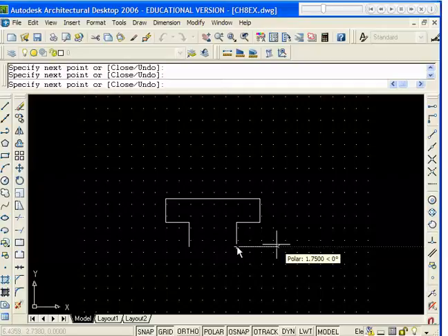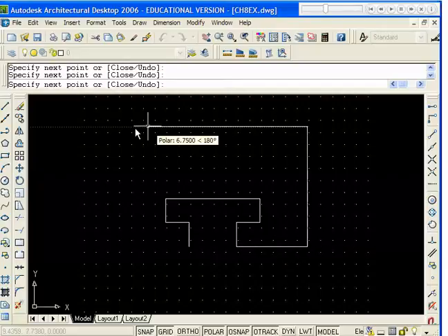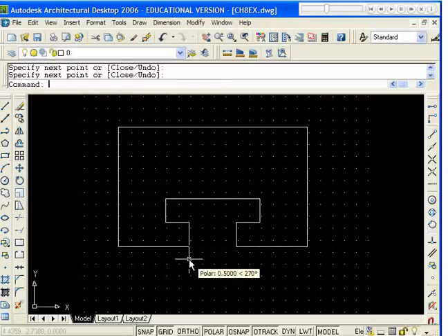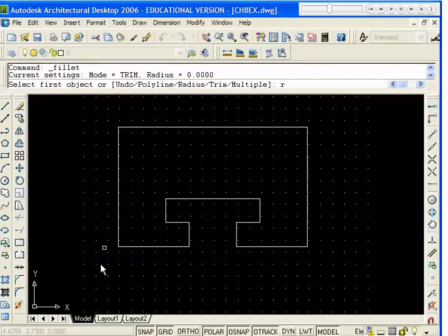And then instead of putting rounded corners on this using the arc command, I'm just going to square it off and draw straight over 3 units. And then I'll go straight up 5 units, back 8 units, down 5 units, and close back to the beginning of the project. And like I said, this project is a lot easier to draw after you've learned some of the modify commands. So for instance, I'm going to use the fillet command on the modify toolbar.